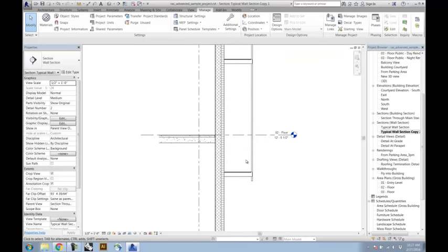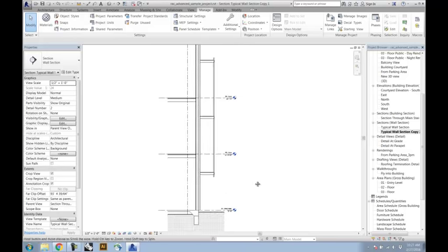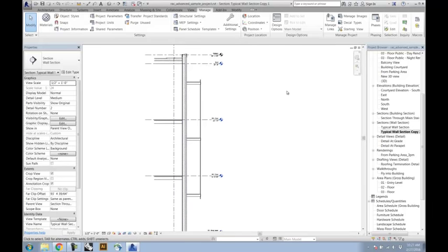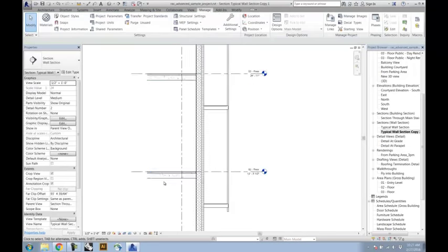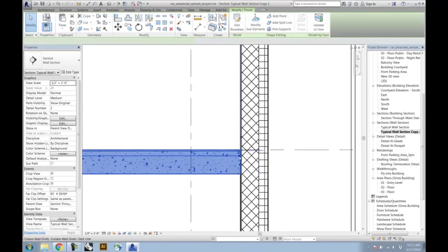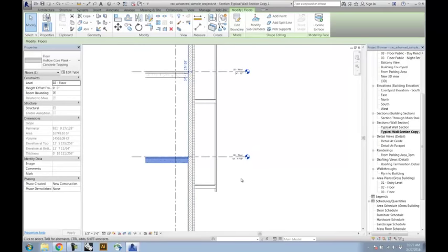I can't encourage you enough to, especially with wall sections, but also with floor plans and so forth, do quick test prints of just a corner on an 8.5 by 11, just to see how the line weights are reading. Even though you're using a kind of automated system, the line weights are always problematic. They always look really Revit-y, and you need to use your own sensibility to actually go in and adjust these settings. Once you've got them set to something that looks good to you, the files will always come off looking much cleaner.